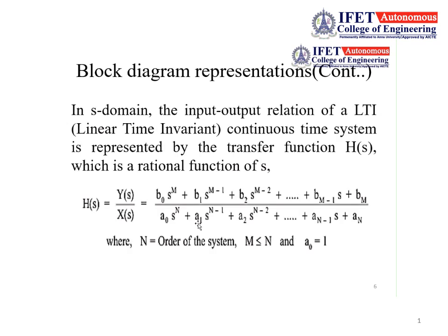If you take the previous differential equation and convert it into the S domain, you will get the transfer function model of the system, h of s equal to y of s by x of s. This can be represented as a rational function of s, y of s by x of s, in this form. We can represent a system in a block diagram both in the time domain as well as in the S domain.